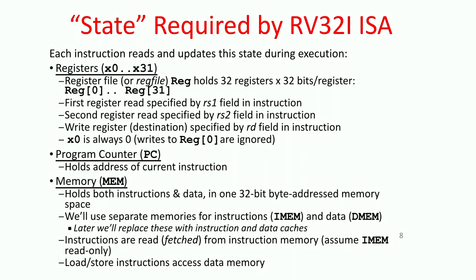And then there's the instructions and the instruction set architecture. The instruction set has instructions for loading and storing data from the data memory. So there's the load instruction that moves something from the data memory into the register file, and then the store instruction that moves a word from the register file back somewhere into the data memory.